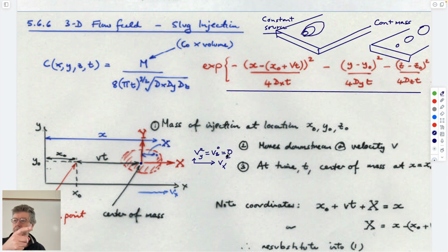So you can have a velocity field, but if you take the principal velocity, the maximum velocity, the orthogonal ones will be 0. And so there's only one velocity in this field. And really what it's doing is it's carrying this mass of fluid downstream and allowing it to spread out as it goes downstream. So in this case then, this would be dispersion.